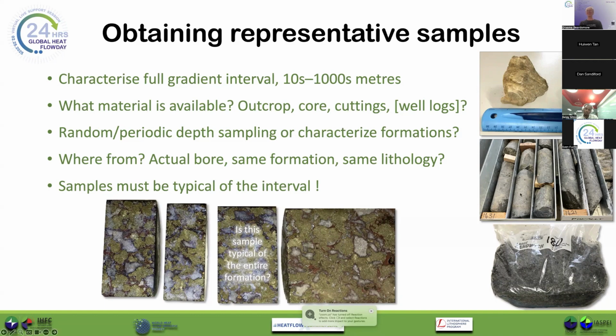So these are what some real samples look like. Hand specimen samples, core samples, drill cutting samples. With the right instruments, we can get thermal conductivity measurements from any of these sample types, but not every instrument can measure every sample type.